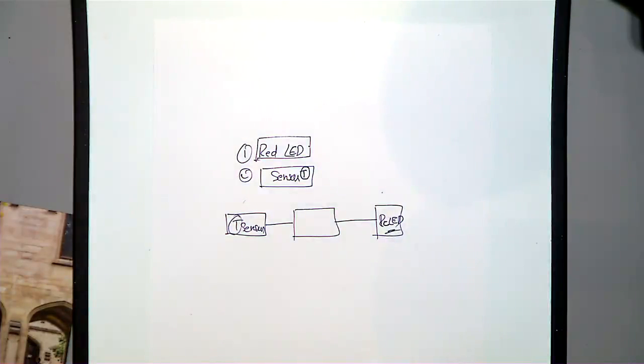Then what is the middle part? As I said, you don't need a microcontroller. Obviously, you can design with a microcontroller, but this is a simple system. So you should always think in a simplistic way, then add complexity based on the requirements. You will see some electronic designs that use components unnecessarily, with unwanted logic, which you can cut short. Especially in space-borne systems, because I come from an aerospace background, they always check your design. It should be a simple design, because complex designs will fail.